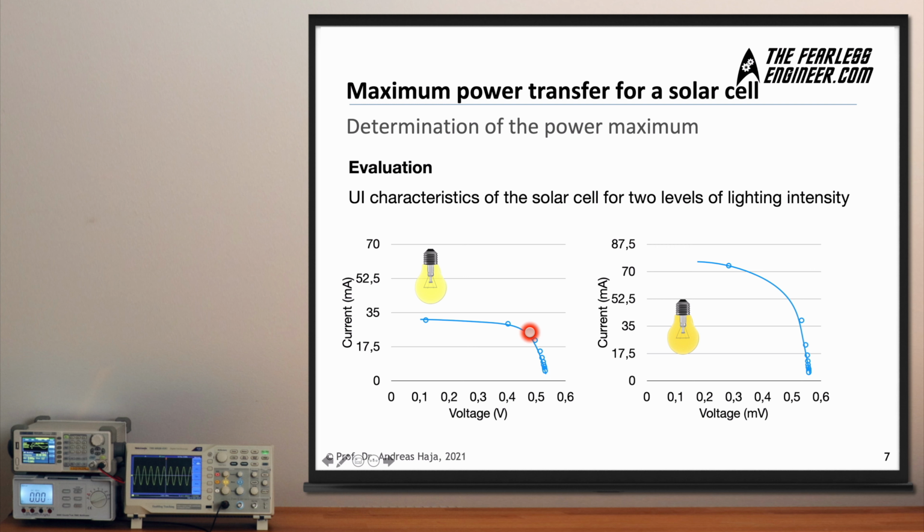But for the first phase here, somewhere between 0.1 volts and 0.4 volts, the current flow remains roughly constant, which is why sometimes, under certain parameters and circumstances, a solar cell is also referred to as a constant current source, because independent from the connected load, it still is able to provide a constant current flow.